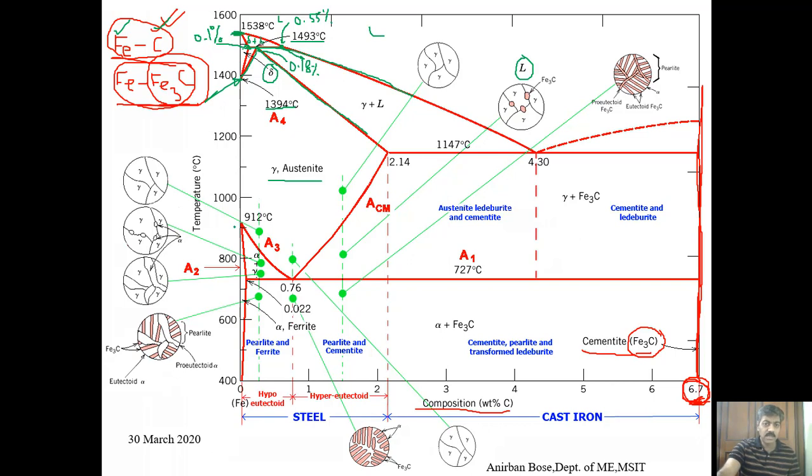Another, in between this range, in this region, is called austenite or gamma iron. So gamma iron is another single phase solution, and it occurs in this region. This is again another solid solution or primary phase, but the structure is FCC. I have told you that delta iron is a BCC structure, but this one is FCC, face centered cubic structure.